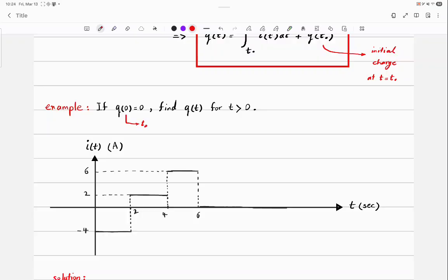This is a confusing topic, especially in the first few lectures. We'll try to do as many examples as we can to just clear that confusion. But I want you to memorize this. If the current enters from the positive terminal of the voltage, it means that if you multiply I and V, it will give you the absorbed power. The other way, it will give you the supplied power. Okay?